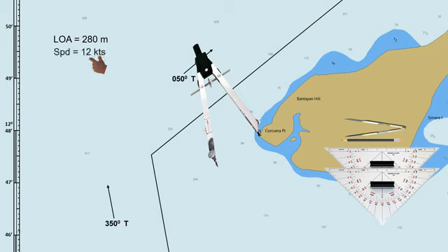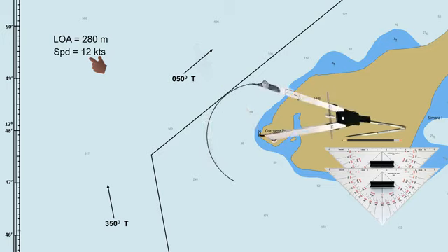This video shows 3 different methods on how to determine the wheelover point. The first method is to plot an arc or a circle where the lighthouse is at the center with a radius of 1 nautical mile. The actual position of the lighthouse is marked with a small circle at the base of the symbol.